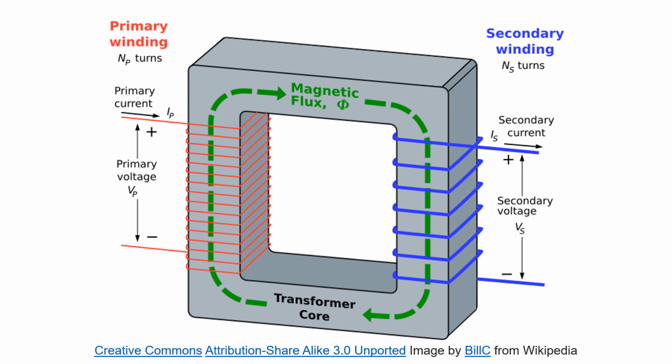This applies only to alternating current which changes continuously. In case of direct current, change occurs only during the moment the circuit is switched on. So practically there is very little opposition to a direct current by an inductor except the minimal resistance of the wire.